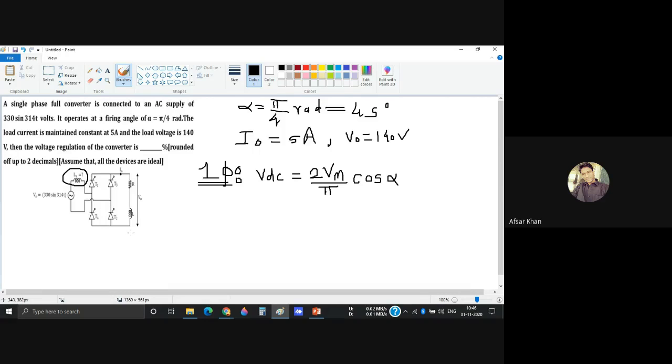Yes, sir. So everyone should focus here. It is a very important problem, and such types of problems are definitely asked in the GATE exam. It is mentioned as source inductance. If there is a source inductance, there will be some voltage drop at the output. Yes or no? Yes, sir. So that drop must be subtracted in the output.